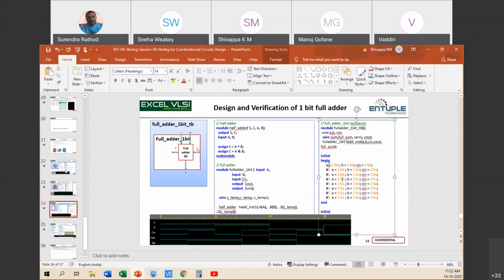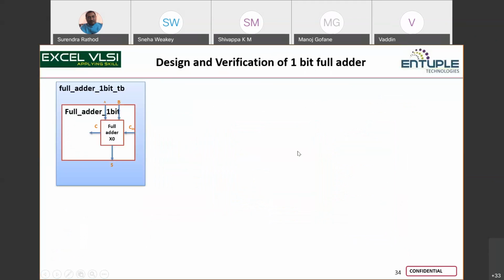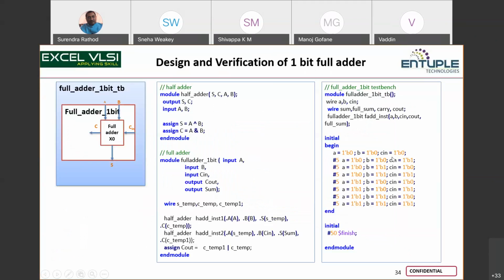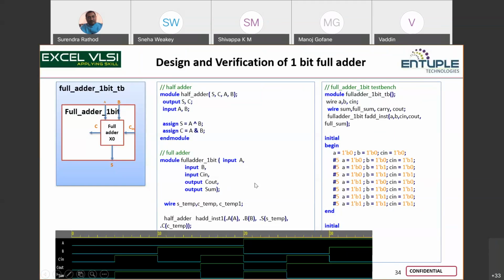In the test bench, I am using all blocking, right? Here, I don't want to complicate. In the test bench, what values I want to drive, I am assigning directly to this input, and then that input test is passed to the DUT, and then further the DUT behaves accordingly.